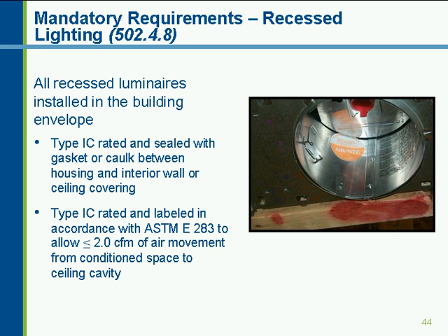So what have we talked about today? We've talked about some of the changes in the R-value requirements for the opaque envelope. I've showed you the new U-factor table for assemblies and a way to meet the requirements if your assembly does not quite meet the R-value requirement. We looked at the changes in the fenestration requirements. One of the biggest changes was that the skylight requirements are now, instead of plastic and glass, going to be just one set of requirements for all types of skylights.